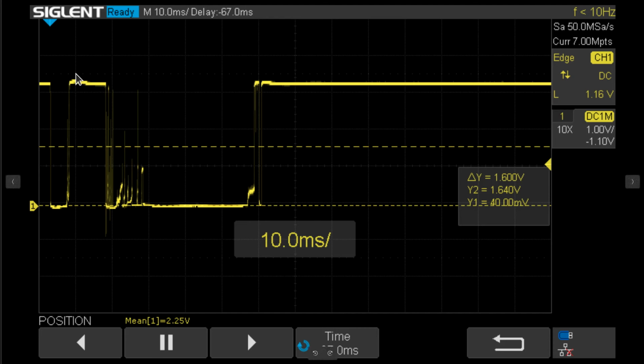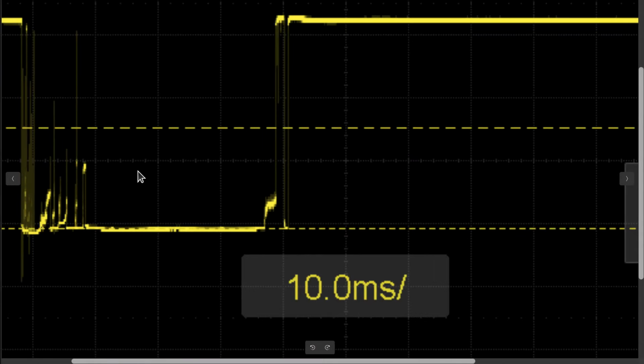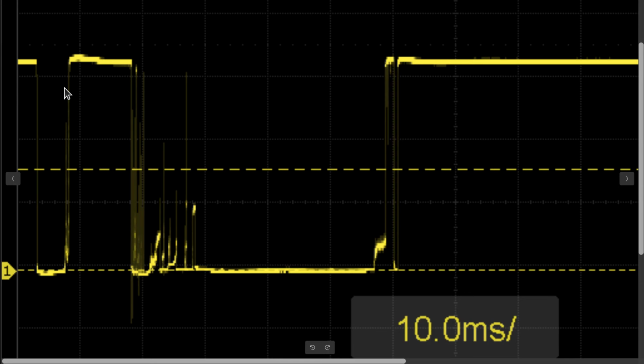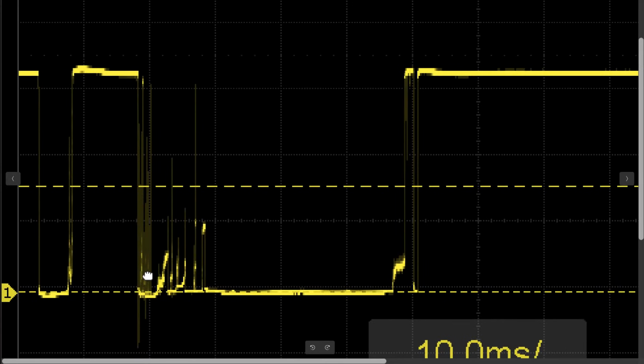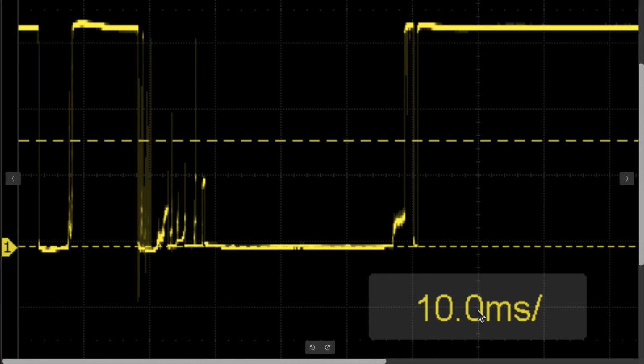And by that I mean it's going on, off, on, off, on, off, on. And if you're running your FPGA and you're looking at this on a GPIO input, you see a 1, then you might see a 0. And if you're polling it in a real fast loop at like 25 megahertz, which is the crystal speed on the board you're looking at, or some of the other experimenter boards could be 100 megahertz or even faster, that is not a particularly fast speed. So, what do you got? In 1 millisecond, there's 1,000 samples at 1 megahertz. So this is 10,000 at 1 megahertz and on up from there.